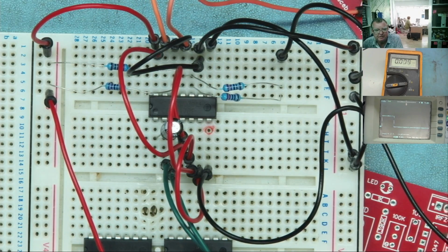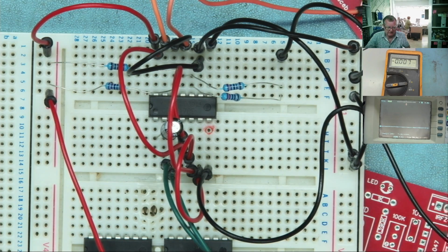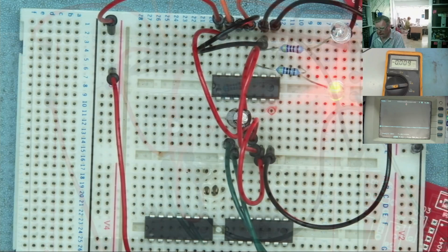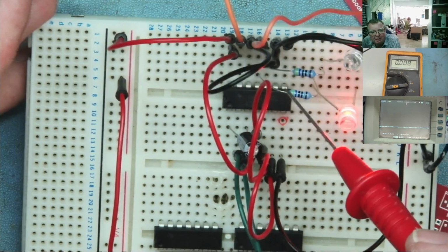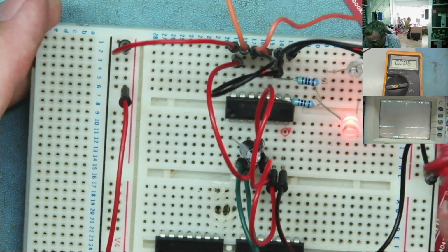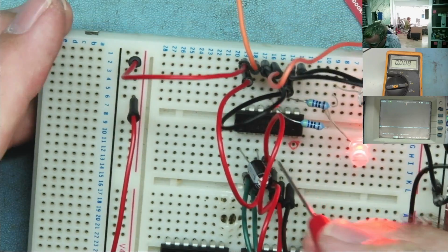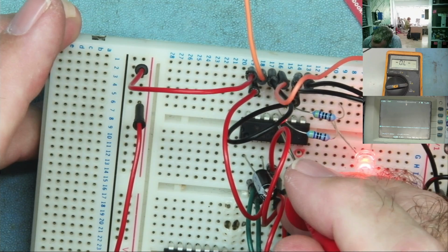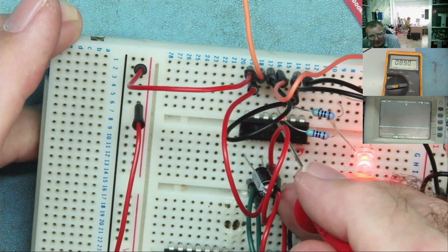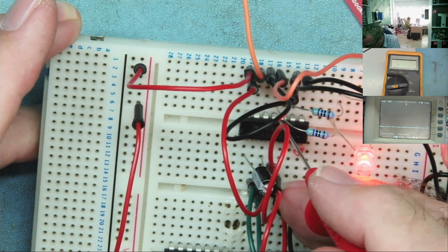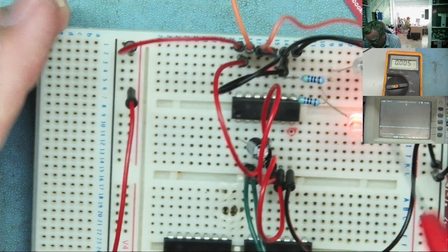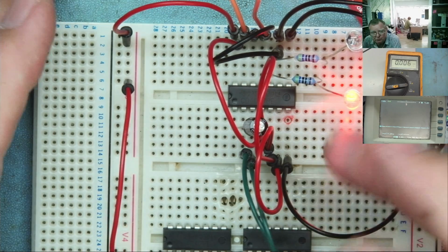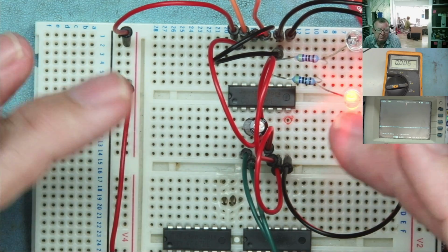There's one more thing I want to test, which I thought of, and then we'll have a look at these chip testers. I've reconnected the LEDs. I may have them the opposite way round now. I didn't really check. The different one is lit up, but occasionally it did actually switch around before anyway. Yeah, still at about 2/3 of the supply voltage. Pin 10, basically 0, okay. So what I'm just wanting to test is this problem to do with decoupling?